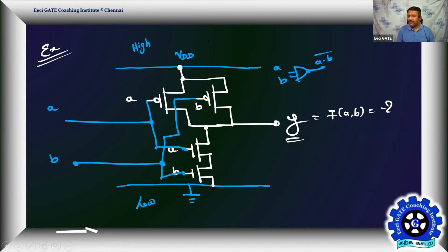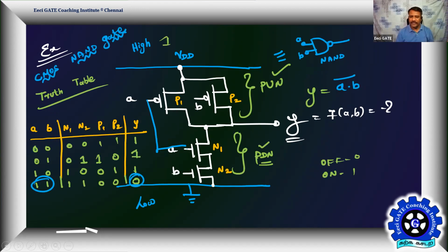Hope it is clear, everyone. Yes, sir. Okay, that's NAND logic. So we are making an important conclusion. Parallelly we are getting the budget. How many transistors are needed to implement one? Not transistors, it's the CMOS budget. Or exactly speaking, two transistors. One CMOS is two transistors, one PMOS and one NMOS. So you can multiply the number of CMOS by two, and that many transistors we use for that implementation.